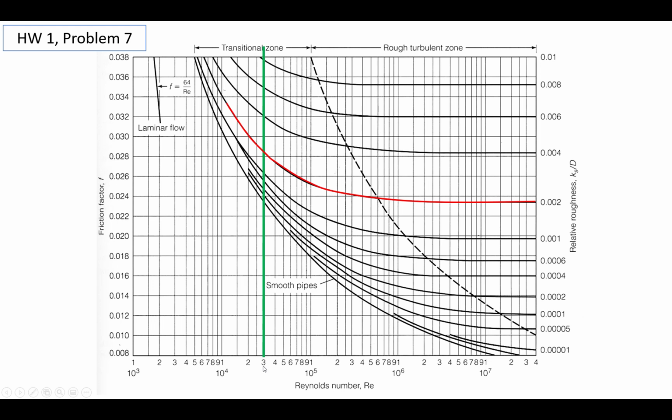Okay, and then from there, you shoot over to the left and look for the intercept on the vertical axis on the left side of the figure. So the final step is going over to the side. So that's not 0.028. It's not 0.30. I mean, it's very clearly above 0.28, but it's not quite halfway. I think that what we could say is that the F value there is 0.0285, because it looks like it's about halfway between 0.28 and 0.29, maybe a little more than halfway potentially.